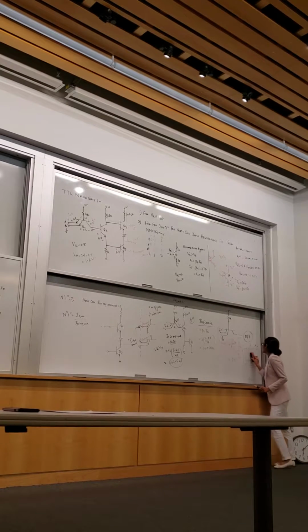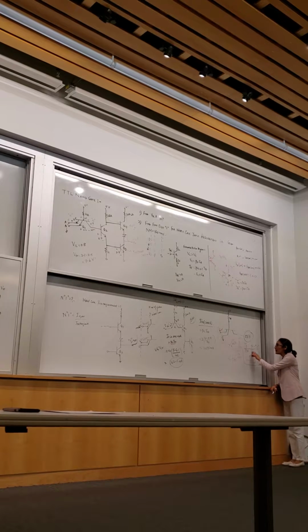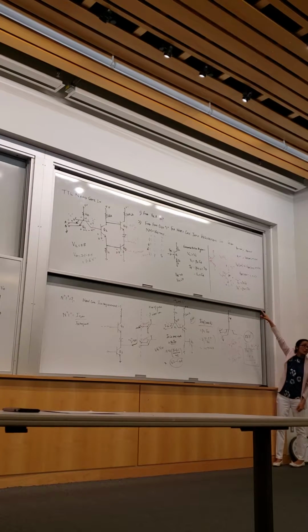Now what we are saying is, let's say we have two emitters in the base, and they are N-type, E1, E2. Now one of them is at 5 volts, another one is grounded. You see, this is an NPN transistor, just a part of the whole big transistor. If nothing is flowing here, this itself is acting as an NPN transistor. That's your lateral transistor. So whatever input is at high logic, that's your collector, and the other input which is at low logic, that is your emitter. And the gain associated with this transistor is represented as beta, which is 1. That's given.